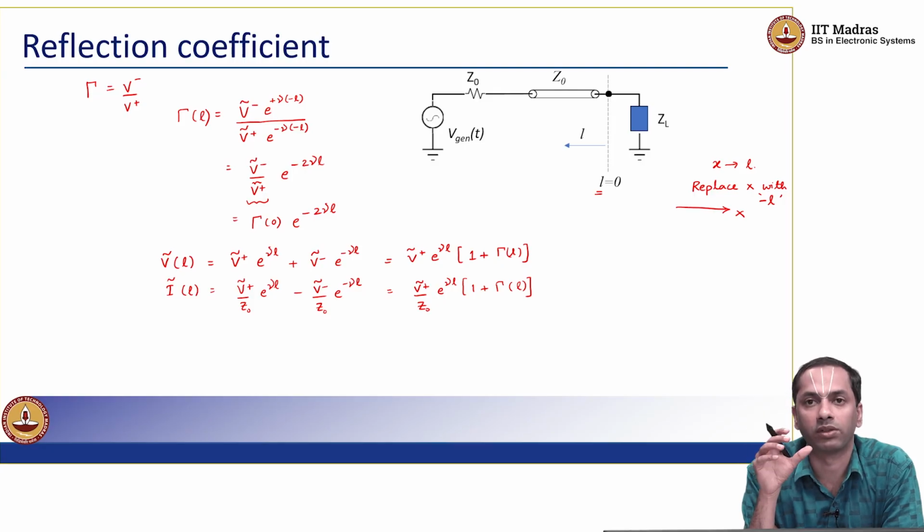Okay, so we are saying that at every point along the transmission line, the voltage or current will have a sinusoidal motion to it, right? And that in order to get the entire picture of this sinusoid, all I need to know is the amplitude of the sinusoid and the phase of the sinusoid with respect to the forcing function, which is the generator voltage.